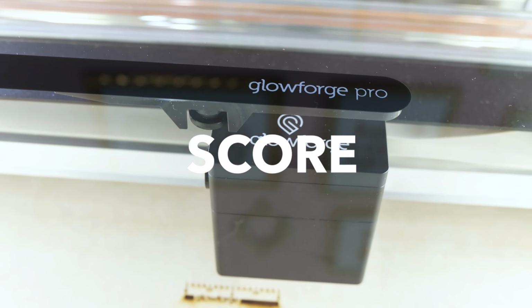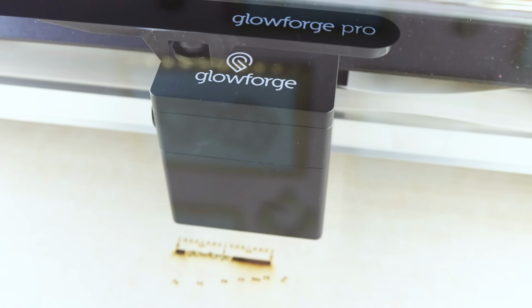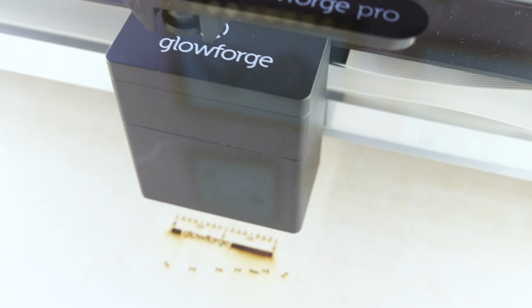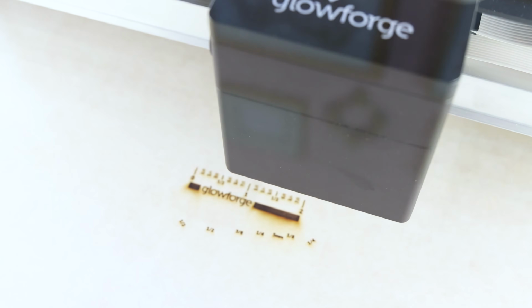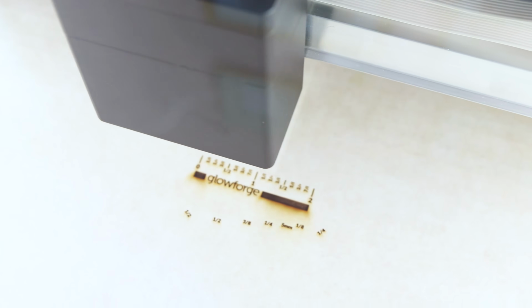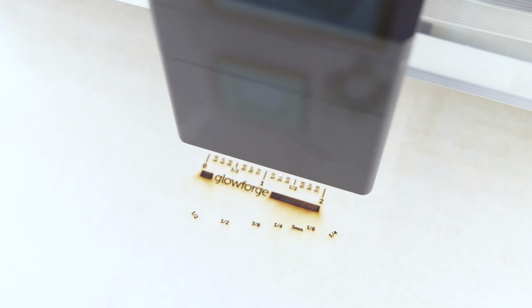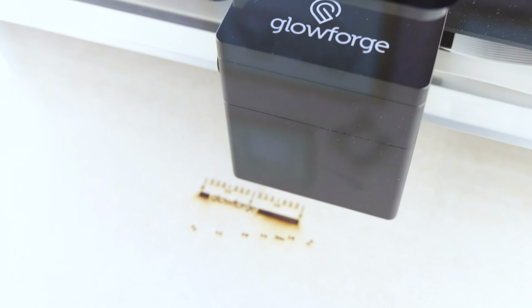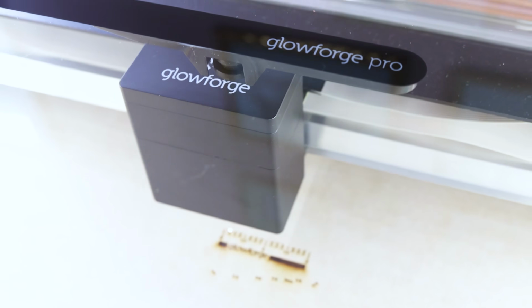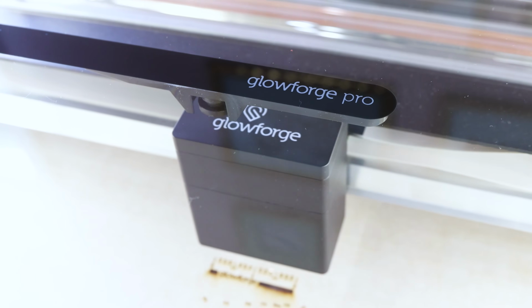Score. Kind of somewhere in between the two. Moves at a slightly lower speed than an engrave, and a lower power than a cut, and follows a line path to create a divot, but not cut the material fully through. You may find that you'll choose to change designs intended for an engrave over to scoring if it will achieve the same effect, as it can save you a significant amount of time on a project.